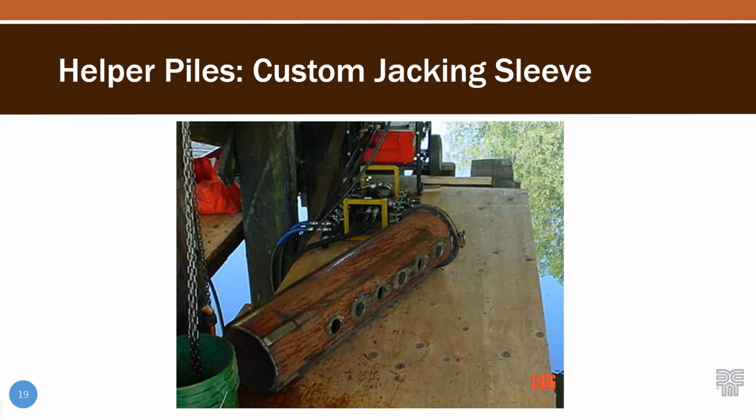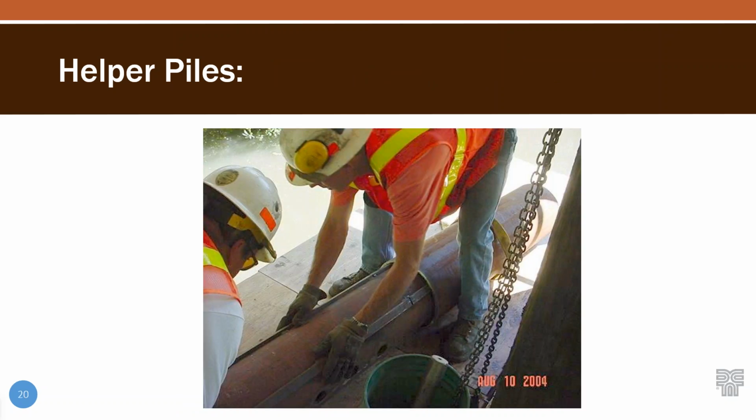So one of the other issues with jacking piles is that you jack and you have whatever your throw of your jack is. Well, your throw of your jack is measured in inches and the depth of pile that you're going to do is feet, right? And so you jack, shim, jack, shim, jack, shim. And so this has this custom sleeve that was built here with those holes drilled in it for a pin to go through. And what they do is they slide that inside their new pile, and that just helps them with that sequence of jack, shim, jack, shim, jack, shim, so that they can get it installed quicker.